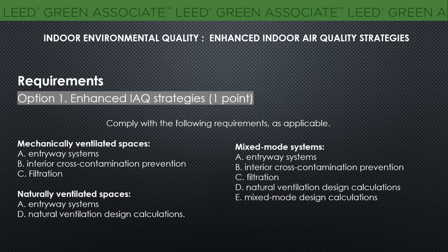slide. For naturally ventilated spaces, an entryway system can also be provided. Natural ventilation design calculation can be done. For mixed mode, which is a mixture of mechanical ventilation and natural ventilation, these requirements are almost the sum of these two: one, entryway system; then interior cross contamination prevention, filtration, natural ventilation design calculation and mixed mode design calculation.